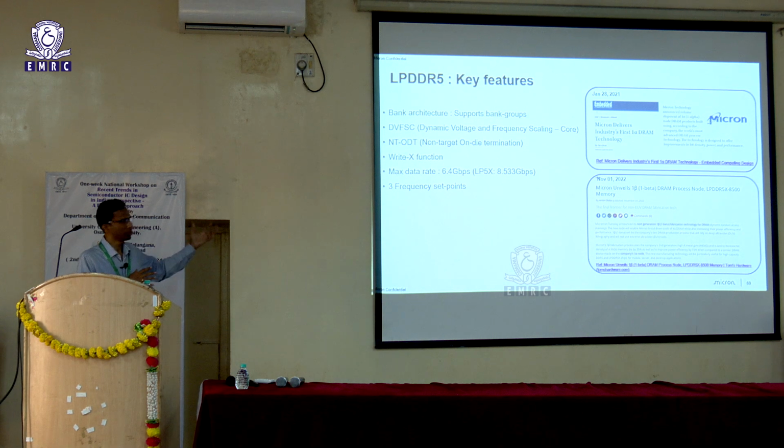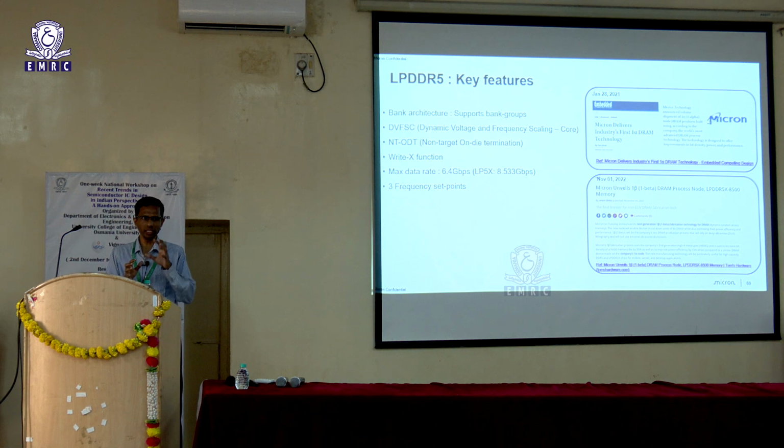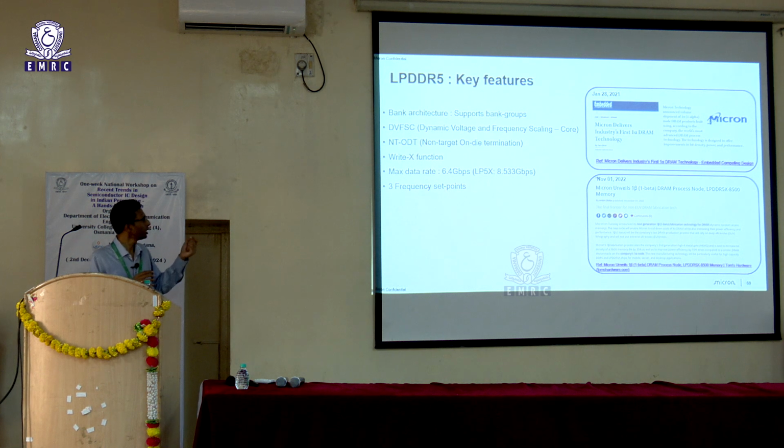So that is something that you will actually see happen in the DRAM chip. If for a significant portion of time DRAM is going to be used in a low power mode or a low frequency mode, you can actually bring down the voltage for some portions of it, so that the effective power that it burns will be lowered.